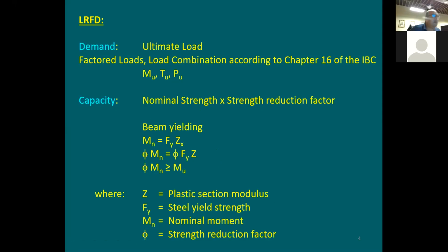Most likely you're going to be using LRFD these days when it comes to structural steel. ASD is more conservative. It's going to give you larger steel sections. Don't forget, ASD is like the old method, and LRFD is like the new method. Let me tell you the reason.